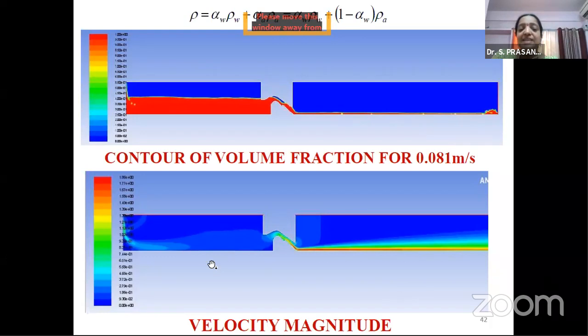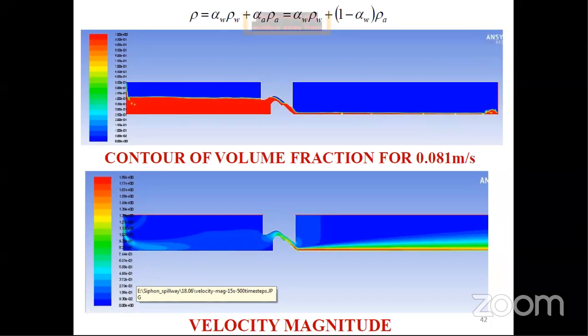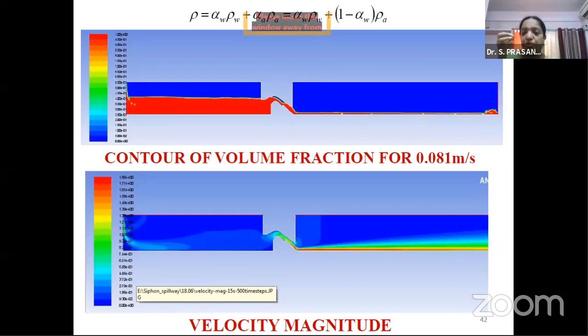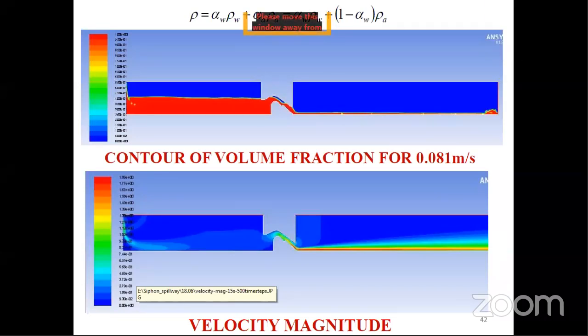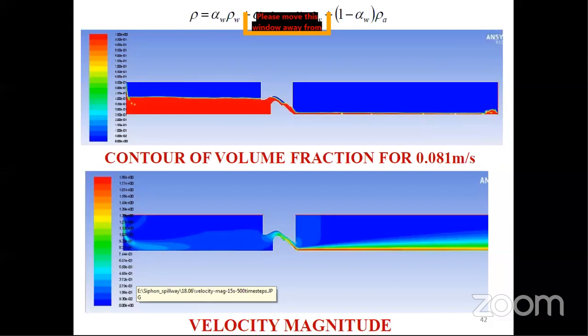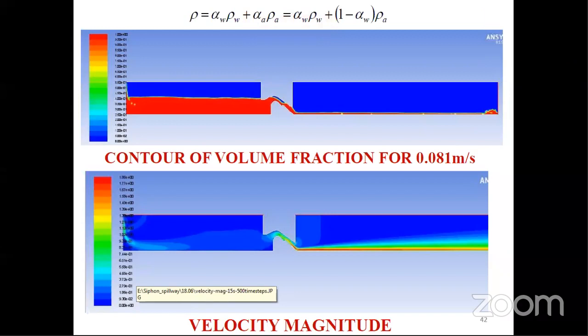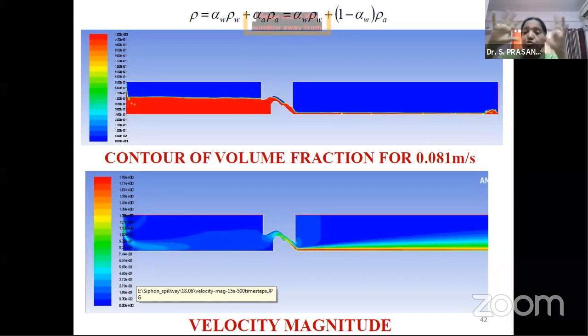Ramya, the case is that when you have cavitation encountered, that is because of the negative pressure. So in the case of spillways, the negative pressure becomes a very, very important parameter. When cavitation is possible for that particular problem, obviously the same thing you are going to model here, right? If analytically you get negative pressure, this also should give negative pressure. If it is not giving, then it becomes a big question mark. Then you have to think what might be the reasons and how you have to change your model, so that you can match it best. Change is not manipulating.